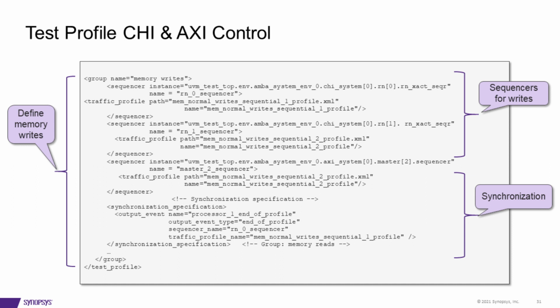You can also create a profile where you just specify that you want to generate traffic at a rate of maybe 1,000 megabytes per second. If I provide that information, the tool will take it and convert that into AMBA traffic to match the rate which you define, and will drive traffic onto the DUT.